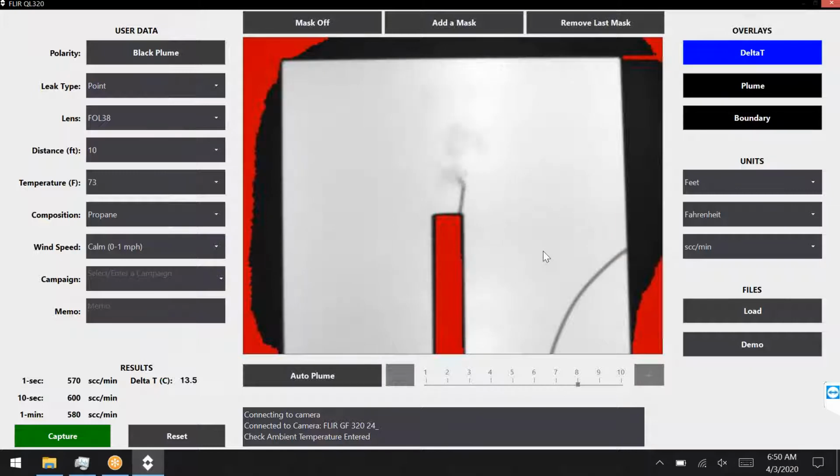So this will be very useful for Q mode. If the customer is going to use this without bringing the tablet into the field, then this temperature screening will help them ensure that the image they're recording in Q mode will be able to be processed later for a quantitative result. Because what you don't want is them taking a bunch of data in the field, getting back to the office and finding out, oh, I didn't have enough delta temperature to apply this method. And I may not be able to go out and take the data again. So I think this Delta T screen feature in the camera is going to be very important for Q mode.